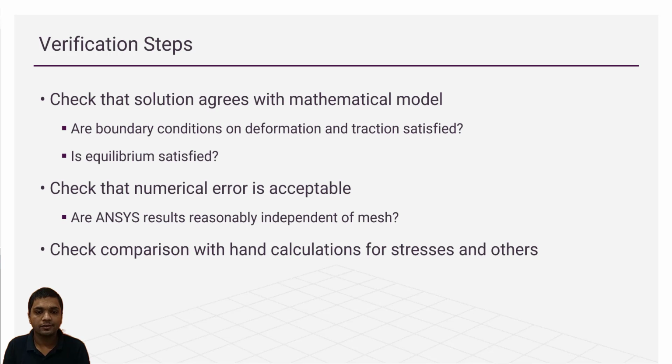Checking with the numerical error, that you can do by yourself by changing the mesh sizes. You will observe that there is not much difference in the results. And the last part is checking with the comparison with hand calculation for reactions, internal forces and stresses and others. So let's do that.